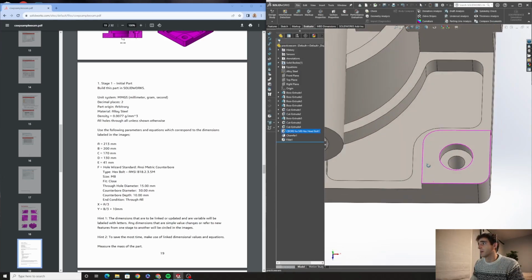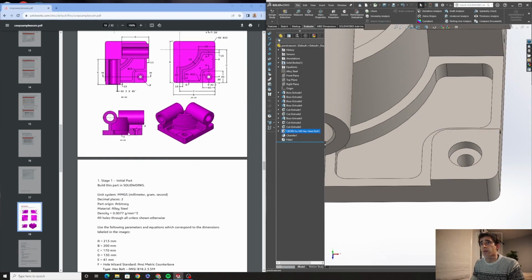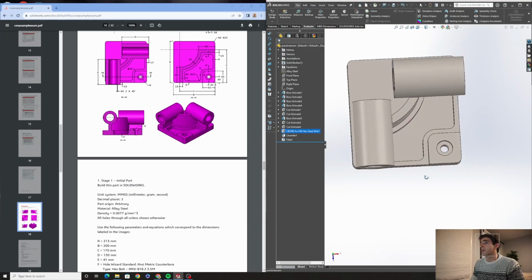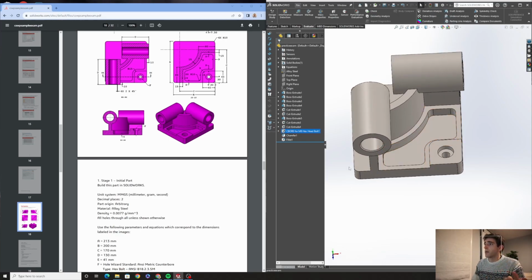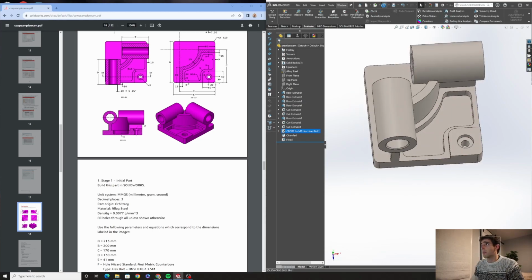Found the mistake. Sometimes you gotta look at things. I noticed the hole looked a little bigger. The things I checked were hole wizard features, make sure my chamfers are right, offsets are the right size, these rib features are the right width, and next was going to be my fillets. Just a few quick things to run through when you're troubleshooting.